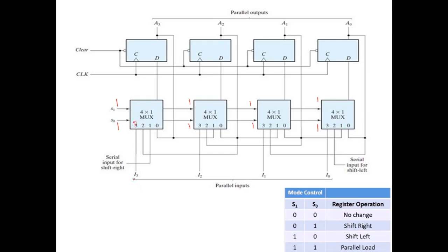So if you connect the external inputs to this D3, then it selects these fourth inputs. That is, the output appears from the fourth input due to the selecting lines being 1 1.